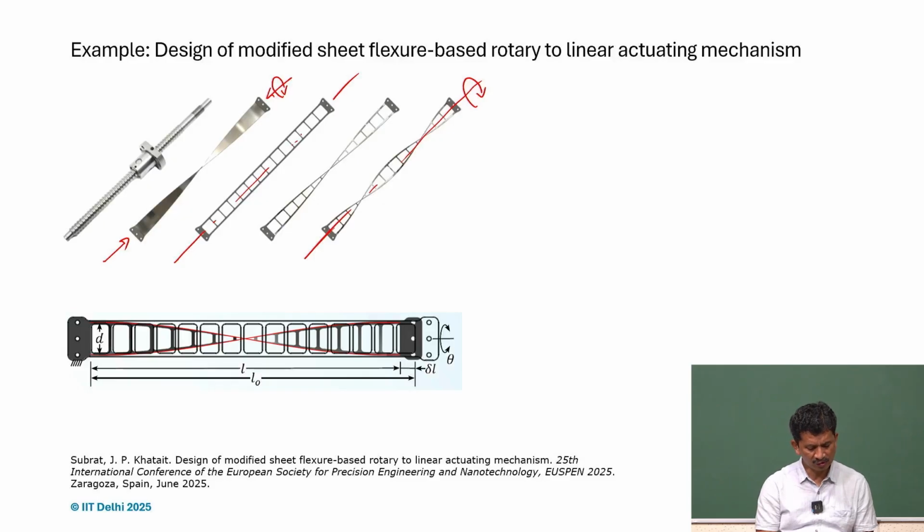At the same time, as we twist, L0 versus L, because the outer edges are still the same, but since we are allowing it to get shortened, there is a change in length, delta L, as we move. It means, again, if we compare with respect to the elastic adjustment, with the coarser movement in theta, we can have a very fine adjustment along the linear direction.